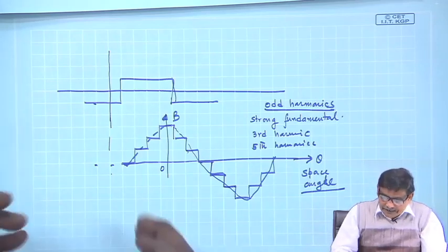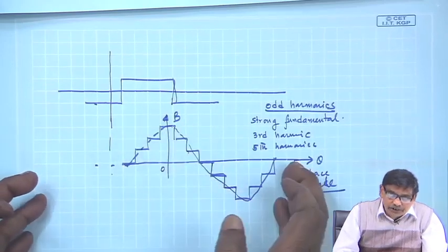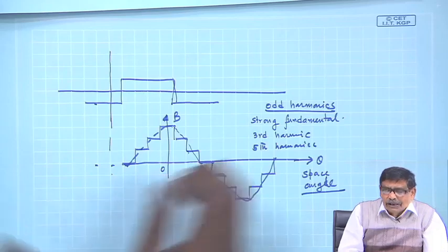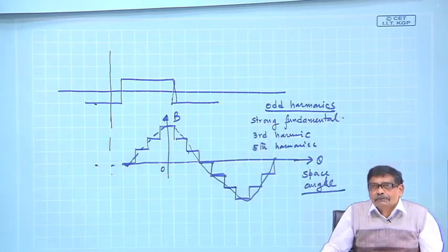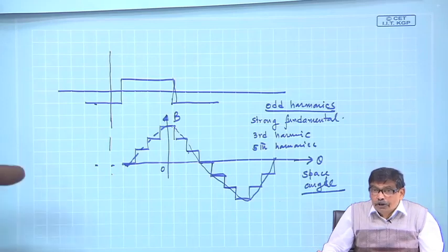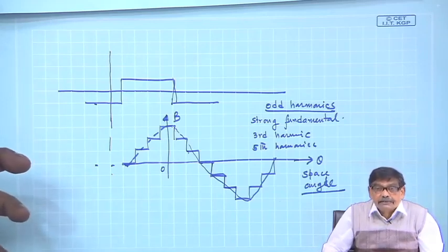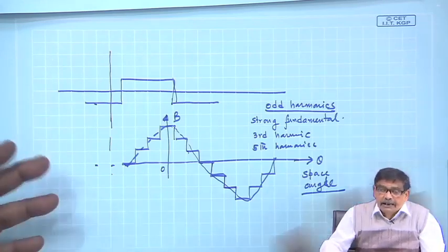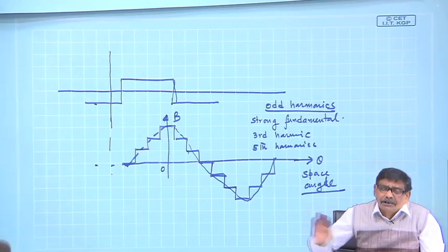I mean, first thing is you have made it more sinusoidal, then you are telling I have done this so that third harmonic will not be there. Third harmonic is the most predominant harmonic. Most predominant harmonic will have highest amplitude among the harmonics. So, if you can neglect that, then okay, higher order harmonics can be eliminated.